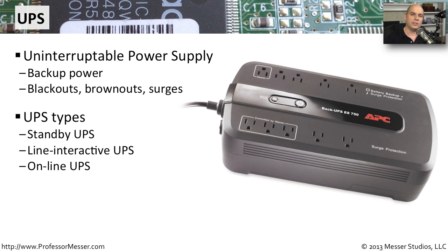That way, the impact to your end user equipment isn't quite as dramatic from shifting from an online state over to the batteries. If you're running in a data center or you're using some equipment that's very sensitive to power changes, then you might want to invest in an online UPS. This is a UPS that's providing power from both the power source and the battery simultaneously. That way, when there is an outage on the main power line, you don't have a delay switching over to those batteries. They are immediately available to you, and your devices have no idea that anything changed with its power source.